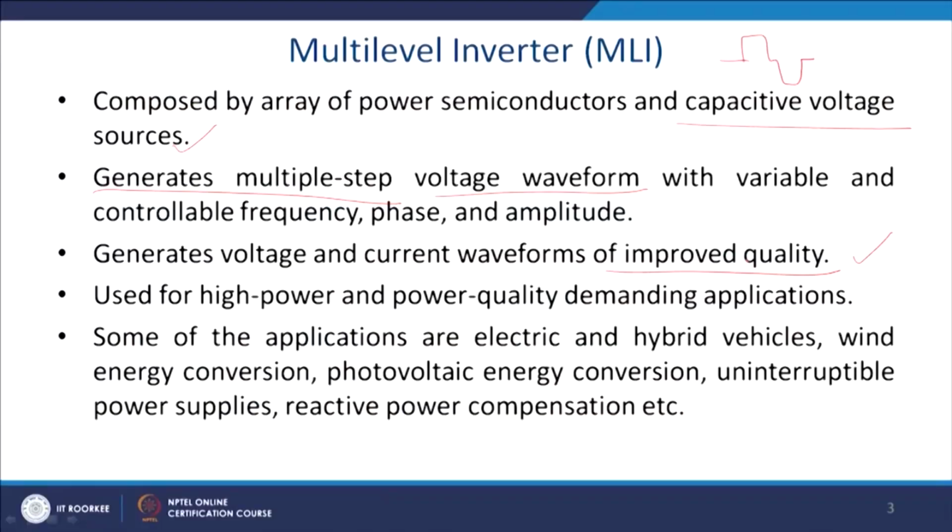the bus method, like when you have a bus with a maximum power quality problem, you connect that device and it will mitigate that problem, that is UPQC, unified power quality conditioner. Or if you ensure that you are giving good quality voltage, but you have a problem with the current, then you will generally go for shunt compensation, and shunt compensation has to be done by a shunt active power rectifier or compensator or shunt active power filter.